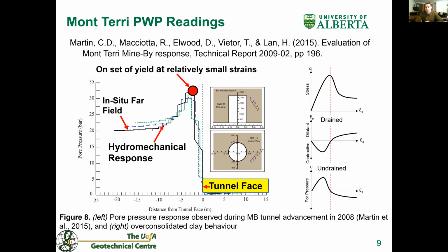Based on the current fundamental understanding, we would expect there to be a slight contraction of the ground leading to a small increase in pore pressures, which would then be followed by a dilatant response and a decrease in pore pressure. This decrease in pore pressure would then lead to an increase of the material strength, but this was not the case at the site.